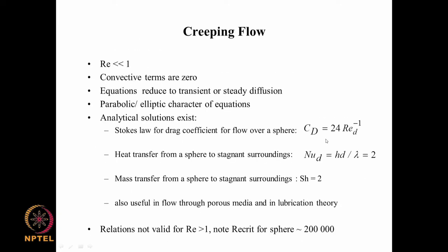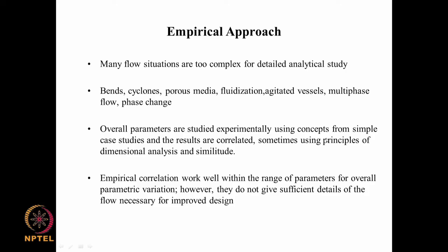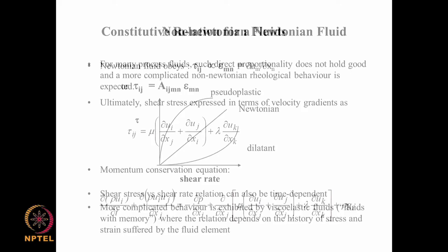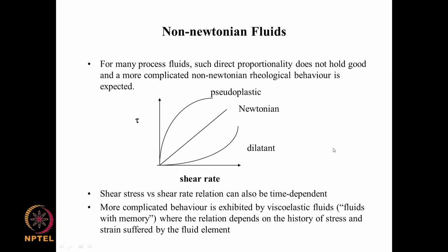Now, but the equations that we have derived are not universally always valid. So, that is another important point that we have to keep in mind when we apply these equations. And one of the simplest situations where the CFD equations that we are writing down, the Navier-Stokes equations, can be questioned is for non-Newtonian fluids. We have made an assumption of a linearity between shear stress and the shear rate or the strain rate, and so that is the linear assumption.